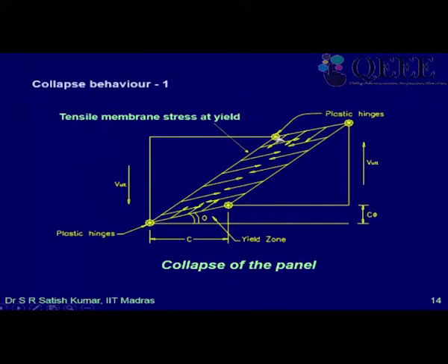Here this is showing a side view, under this type of shear, anti-clockwise shear. So the tension diagonal will be this one, and when the tension diagonal continues to apply the downward pull, the flange which was straight like this will start yielding at this point and this point. This point will be at a distance, let's say C or S, from the corner. The code gives you a symbol S. So this distance can be calculated, and once we know that, we can find out at what load this collapse will occur, and that will be the ultimate load the plate can take.